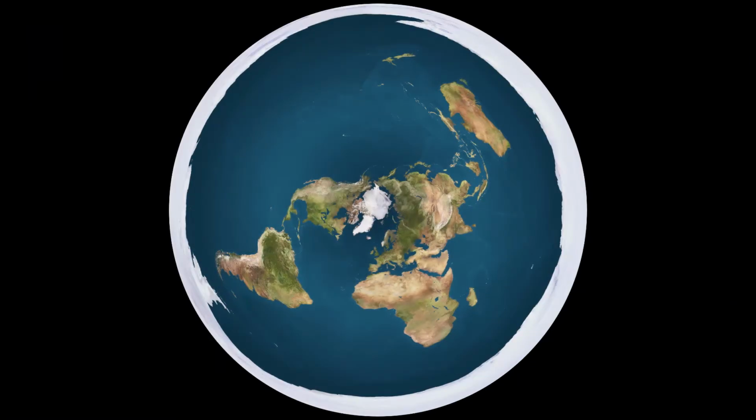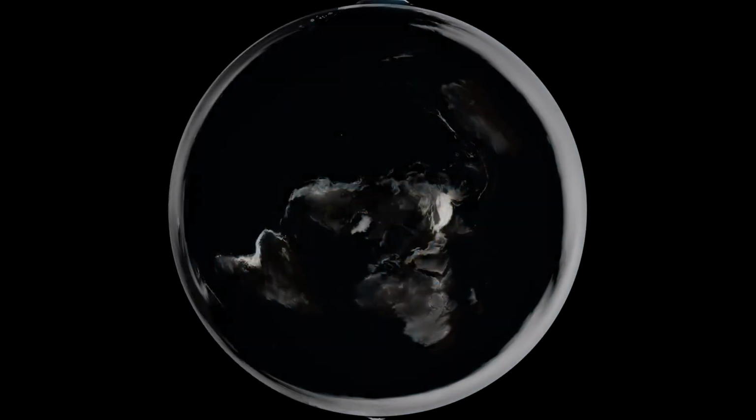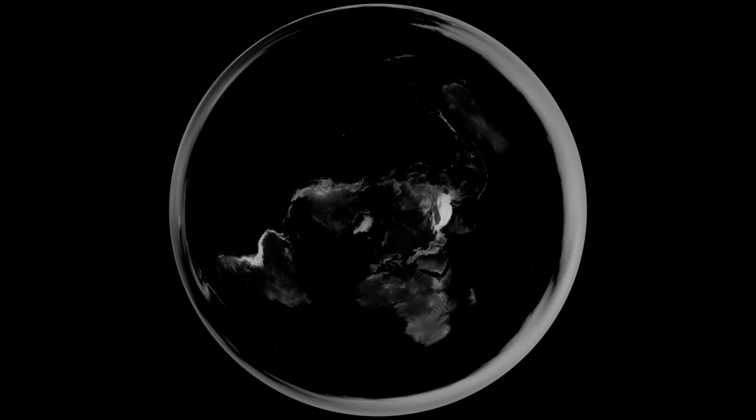Finally, most of the images you will find are Mercator or similar projection. But if you're modeling flat Earth, you need to have them in azimuthal equidistant projection centered on the North Pole. Using Photoshop, Affinity Photo or any image software with a rectangular to polar filter, you can change this projection. First, resize the image to be square. And yes, it will be distorted. Then apply the filter with North Pole settings if available. Do it for every image you'd be using.